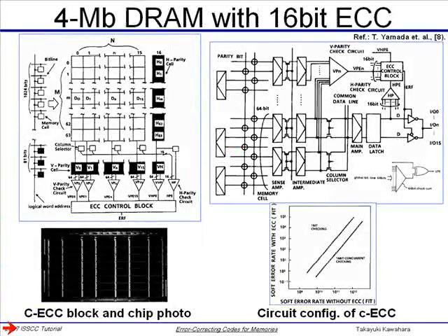So this is mostly the same 1 megabit, with 16 bits. The former 4-bit ECC is a 4-bit parallel operation, and this is a 16-bit parallel operation. So in conquering the Shannon theorem, parallel calculation is an important tool for how to reduce the overhead with the ECC. So how to do parallel calculation is also important.